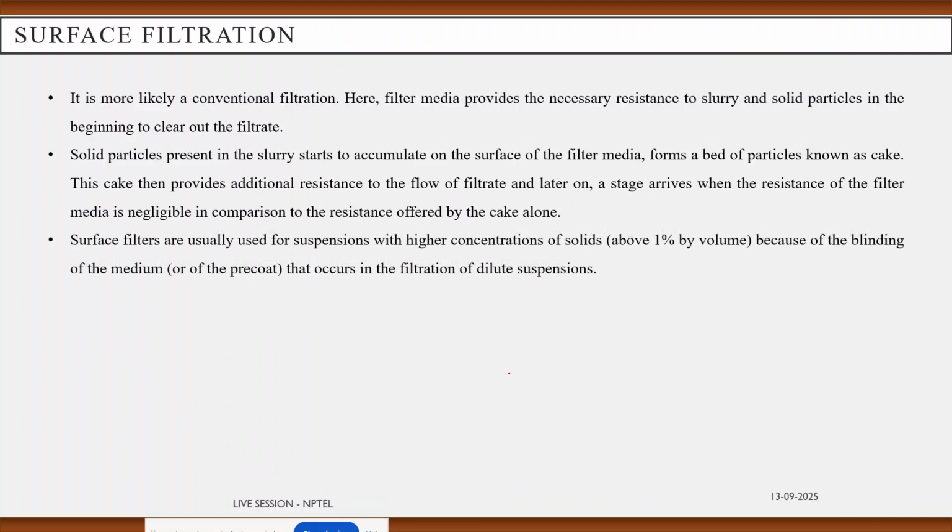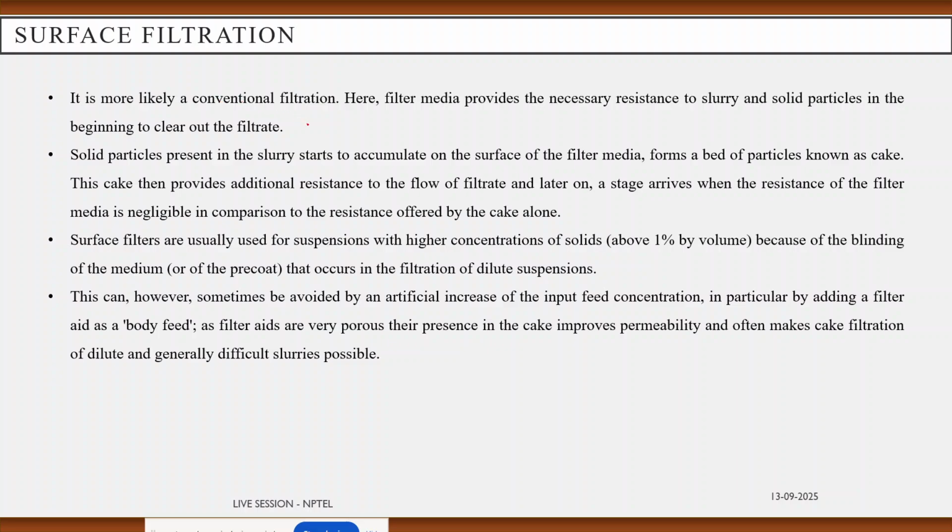So what is happening is more like the conventional filtration that we discussed. Here the filter media provides the necessary resistance to the slurry, and the solid particles adhere onto the surface of the filter medium and start to accumulate, forming a bed of particles which is known as cake. This cake then provides additional resistance to the flow of filtrate, and later on a stage arrives when the resistance of the filter media becomes negligible compared to the resistance being offered by the cake layer itself.